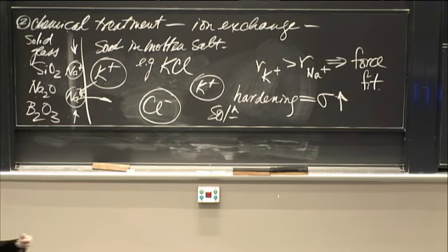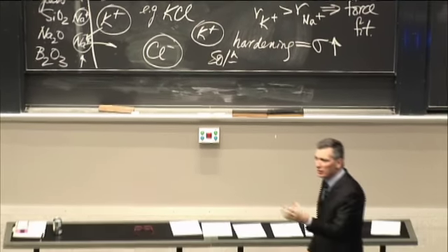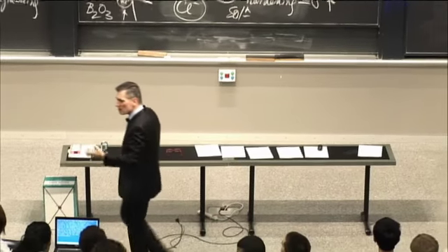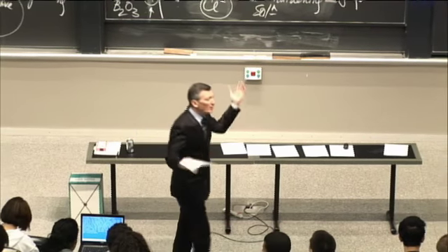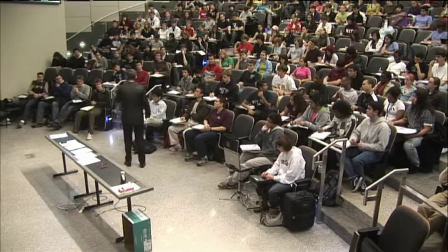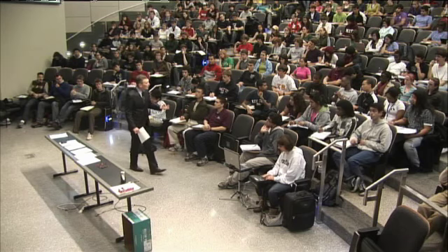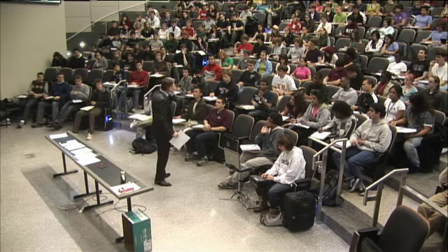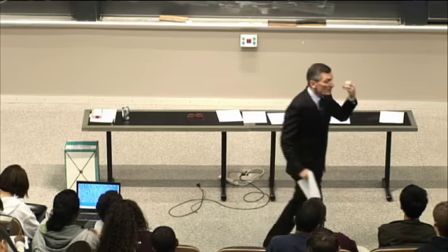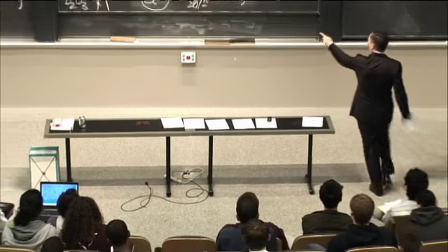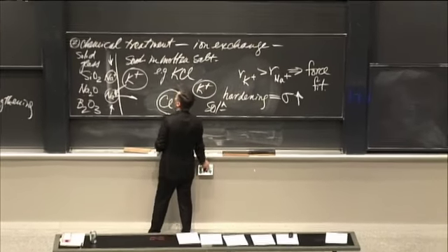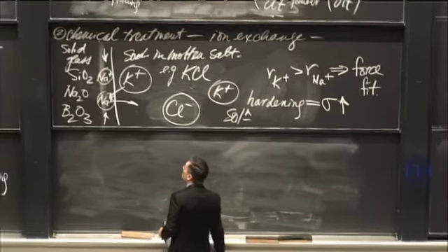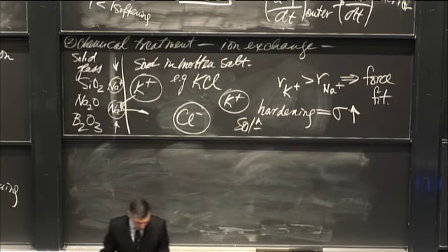We do the same thing metallurgically. If you carburize the surface of a piece of steel, tool steels, for example, surface carburized, so we get hard surfaces that can cut. You say, well, why don't you just put the carbon in all the way through? Well, then the tool bit will be brittle. So you want something that's got toughness in the center so it can take the impact, but it's got surface hardness so it'll cut. And that's an engineered material. We've got one set of properties at the surface, and we've got another set of properties in the bulk. And it's all brought to you by control of chemistry.